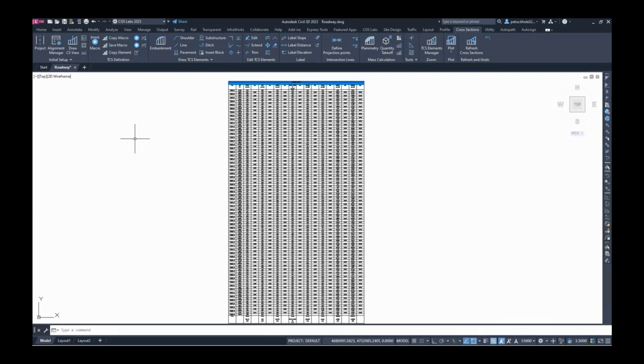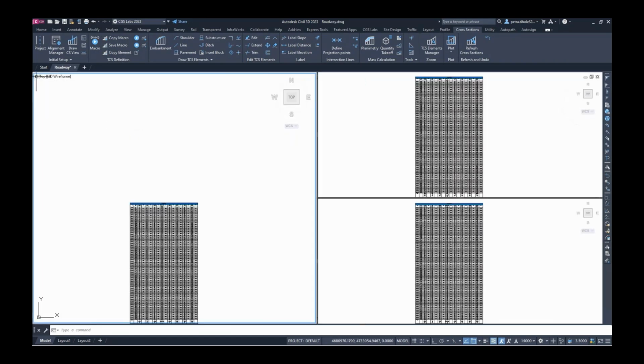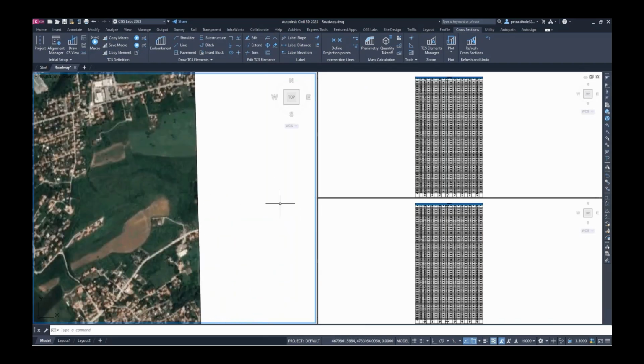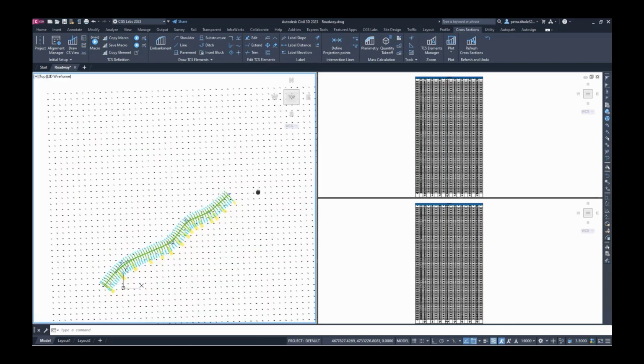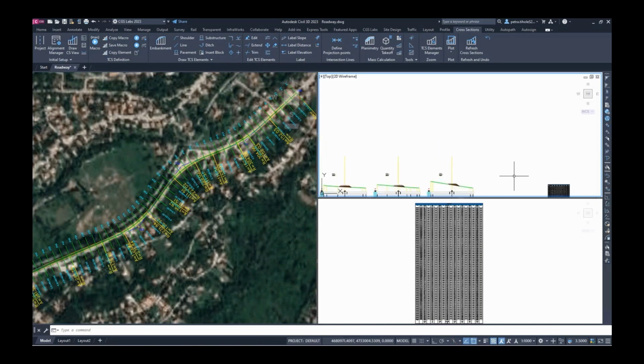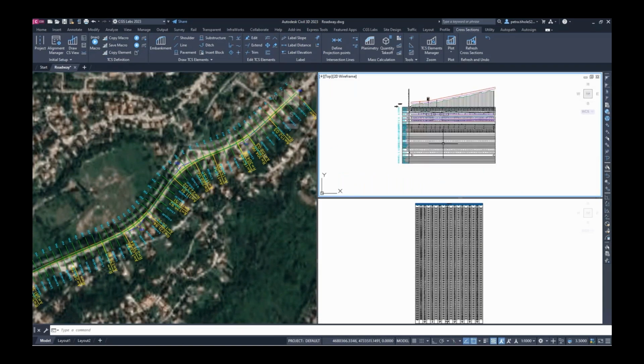Okay, so after completing all the cross sections, you can create a 3D model. However, since we want to make a BIM model, we will first define property sets. These property sets are like metadata that is attached to elements and are the key component that separates a BIM model from a 3D model.